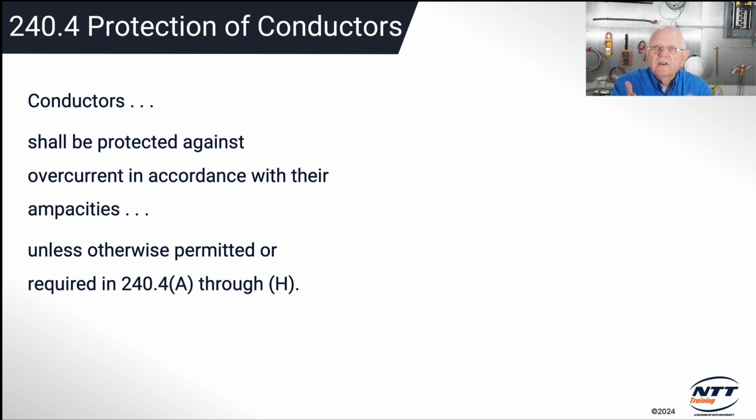Same type of thing, right? You've got that on your dishwasher. You drop a fork down there or whatever, and it binds up. You get the fork, you release the rotor, whatever you have to do, and then there's a little thermal reset button in it. So these thermal resets inside of those hermetic compressors, they'll reset themselves automatically.